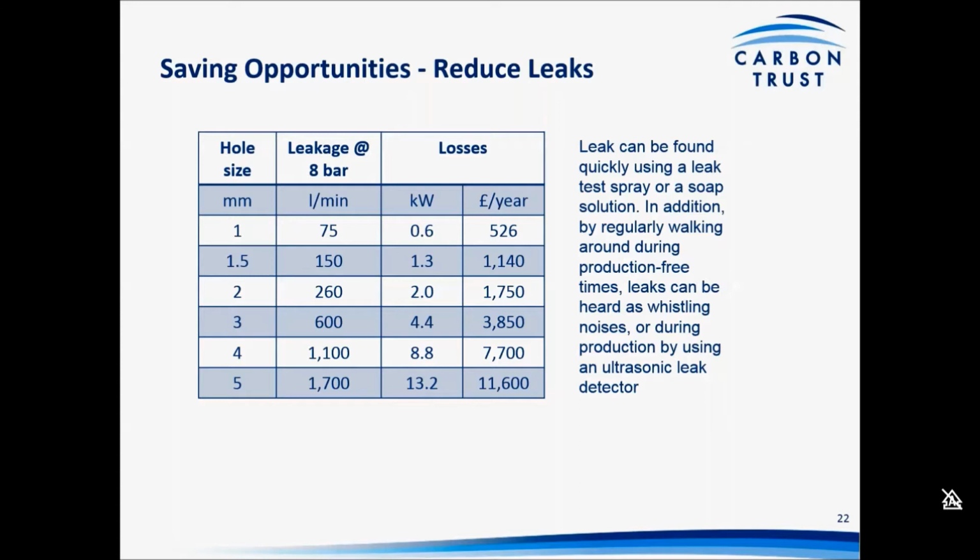Often, the easiest way to look for the leaks is to go in at a period when the plant isn't in production, and just charge the system up, and you'll be able to hear the vast majority of the leaks. So it's obviously a very cost-effective way to do it. It should be done on a regular basis. Certainly the ultrasonic leak detection areas should be checked, I would say, every 6 months.